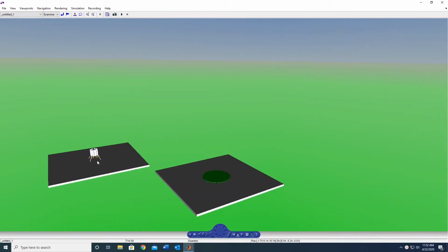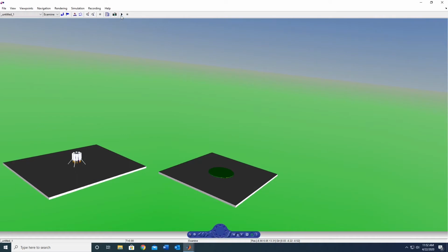It's nothing fancy, but what I can do is I can control this vehicle using my joystick. So I'm communicating with it. You'll see later how we set this up, but in such a way that its onboard computer is fully stabilized in the flight. And if I want the onboard computer to take over, all I have to do is let go of the controls. But if I do take the controls, I can go ahead and fly it this way. I can fly it this way. And the altitude change is also me. I have a throttle here that I can use to regulate the altitude.